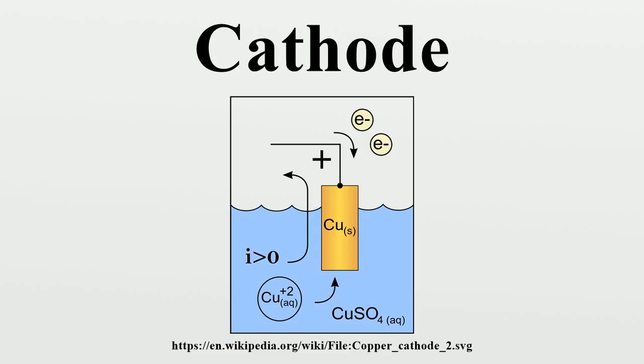The untreated tungsten filament used in early tubes had to be heated to 2,500 degrees Fahrenheit, white hot, to produce sufficient thermionic emission for use. While modern coated cathodes produce far more electrons at a given temperature, so they only have to be heated to 800 to 1100 degrees Fahrenheit.